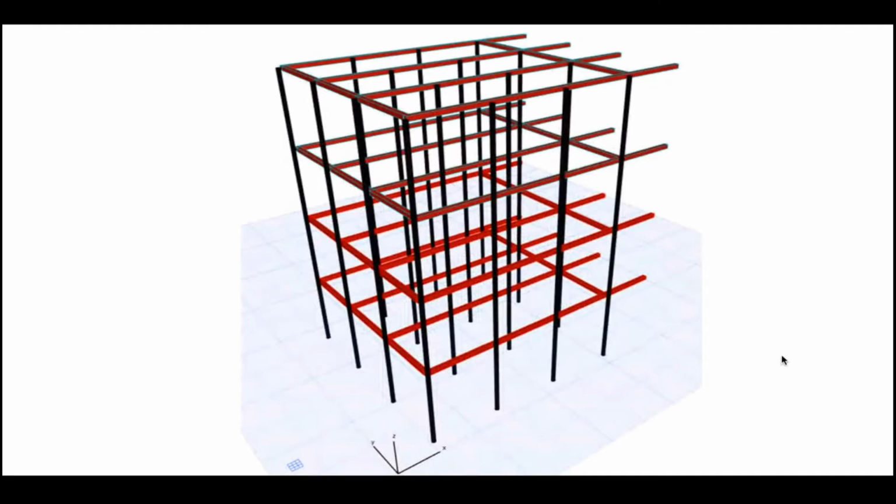So here is a visual representation of how it is solved. If you see all the layers, the cathode nodes of all the LEDs in a layer are wired together. Similarly, each layer will be wired together, and each layer will have one lead to control the whole layer. And similarly, the anodes of all the LEDs in each column are soldered together, and you'll have n cross n leads to control each column.